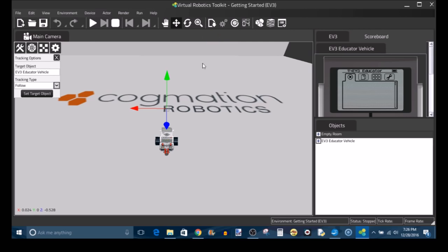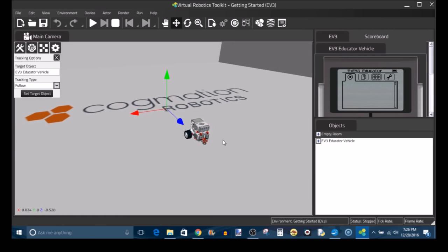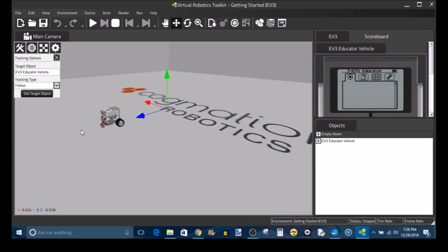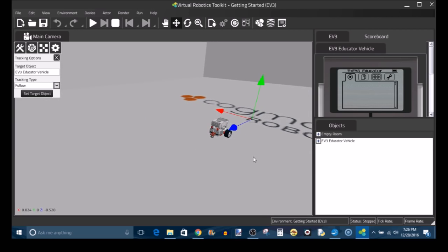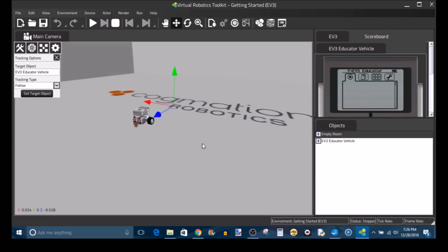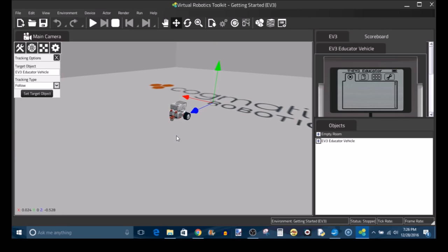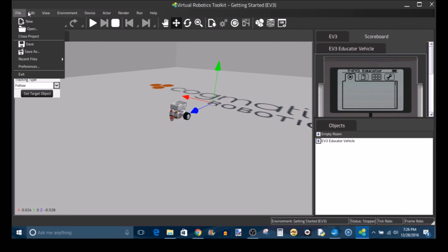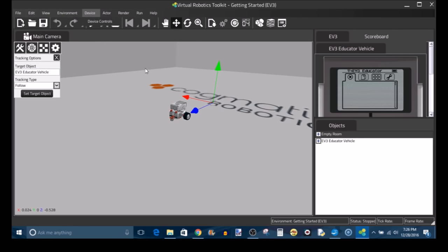You can also adjust the camera here. So using the right click and Alt is the truck camera, which will kind of just drive around as if you're in a car. Control and right click will allow you to pan, and then just right click allows you to rotate around the point that you already are, called the look camera. So those are just the basic camera controls, and I believe that just about covers the basics.